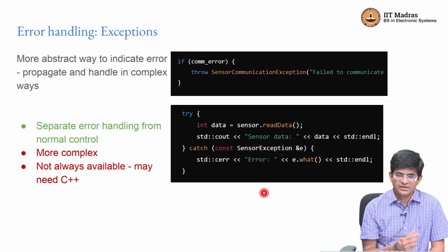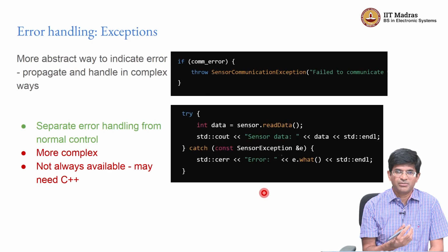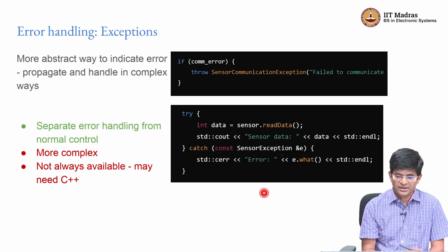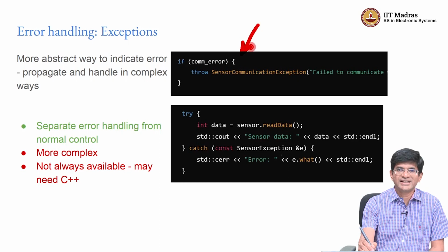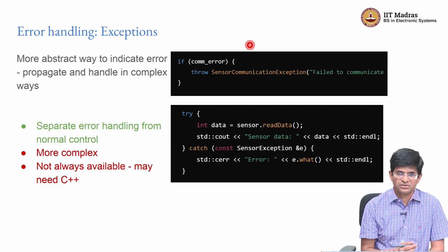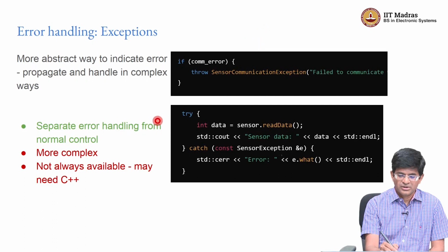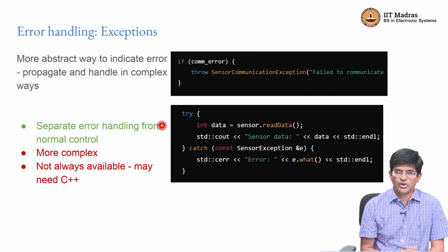There is also the notion of exceptions, which, as we have seen, are related to the idea of interrupts, but are synchronous, things that basically come in software generated, right? So you could actually create a communication exception, perhaps because your communication channel didn't work, right? So you're not able to print something out, but you throw this exception, and maybe there's a fallback communication channel or some other logging channel or something simply to make an LED turn on, right, which basically makes it work.